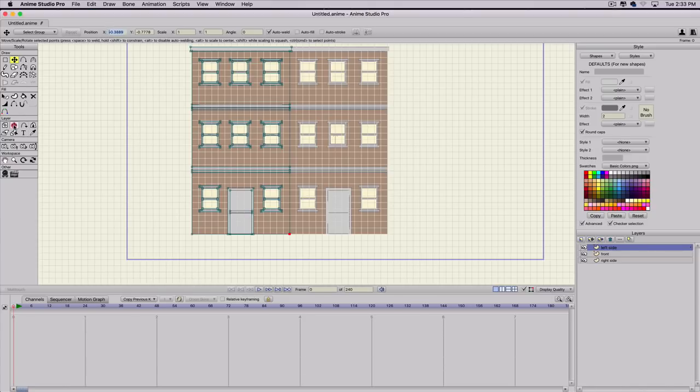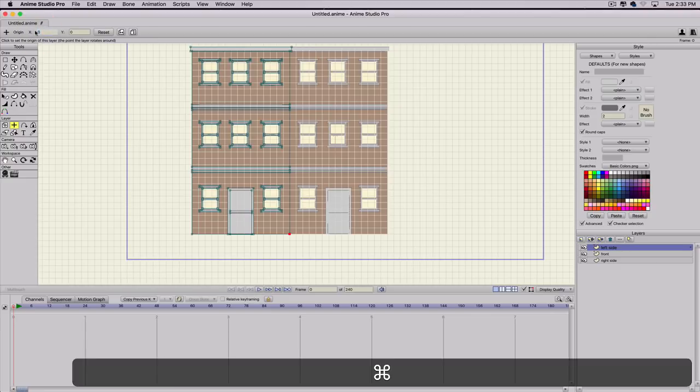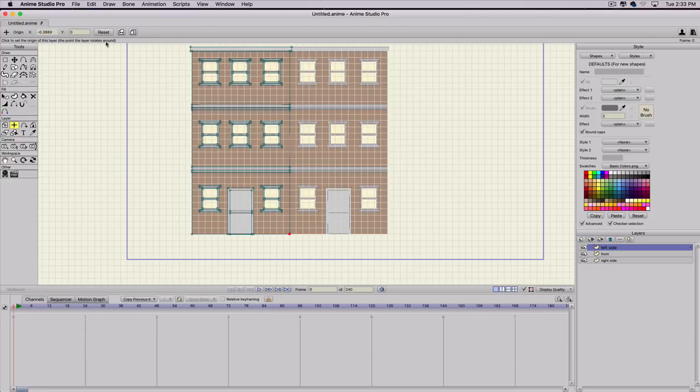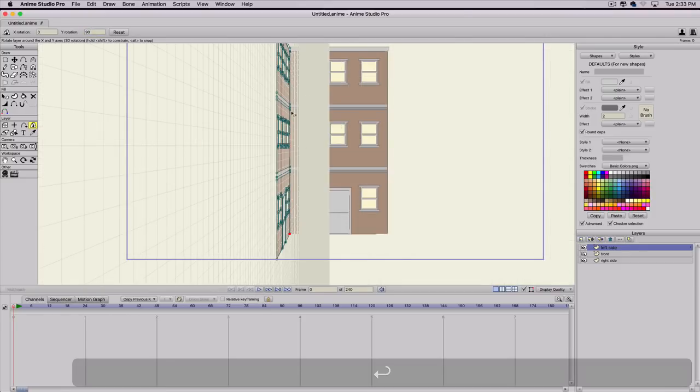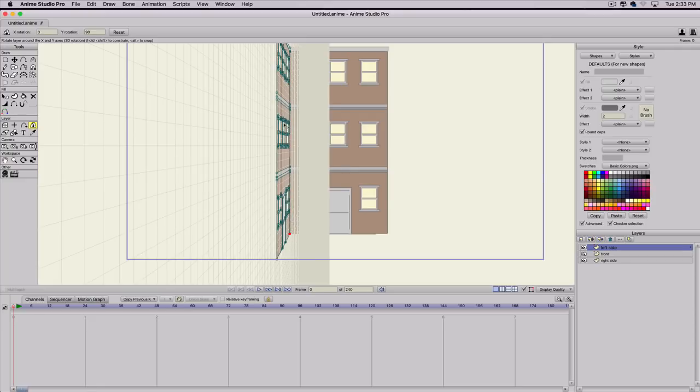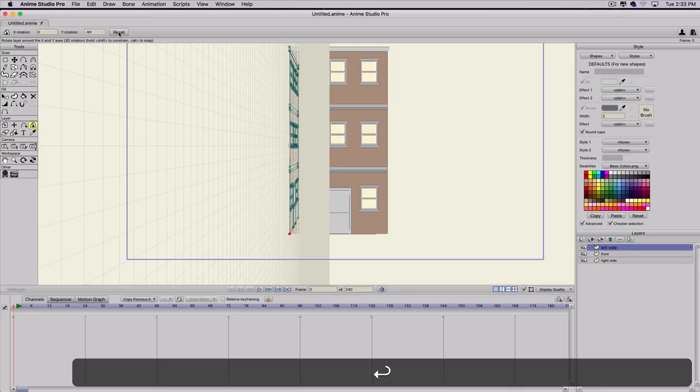And then select origin point under the X. Command V, and we'll paste that. And you can see that origin point's turned right there. Now rotate XY layer, and this time we're going to rotate negative 90 degrees. If you actually mess up, see if I type in 90 and hit it, it's actually rotating forward. So we need to actually do negative. So just put a negative in front of that and hit return.